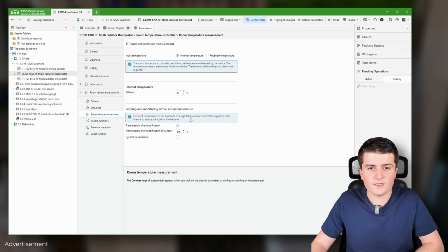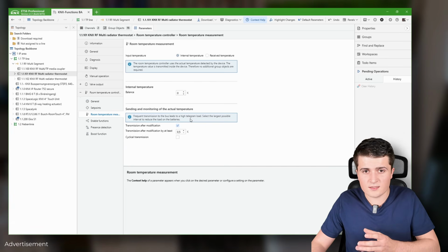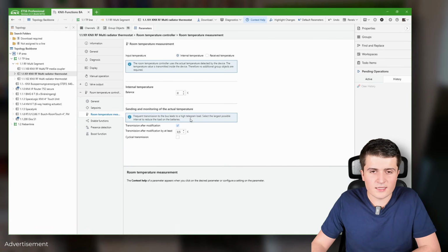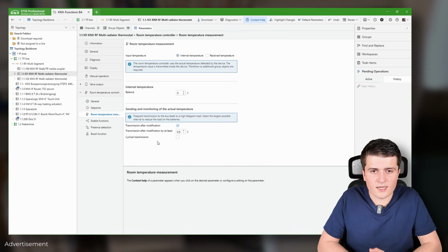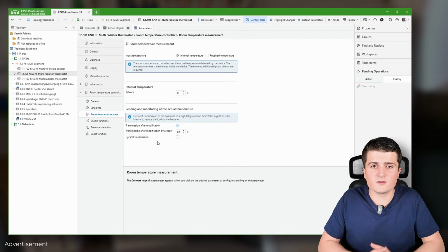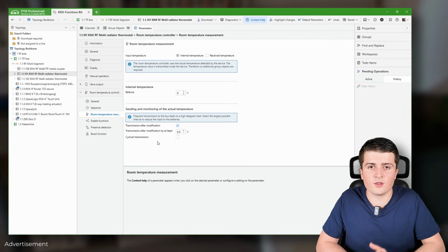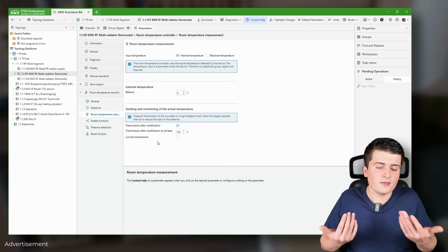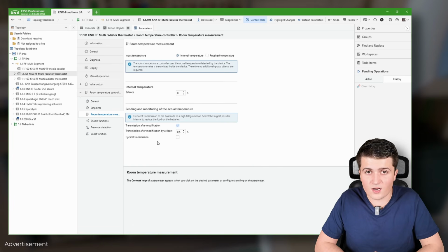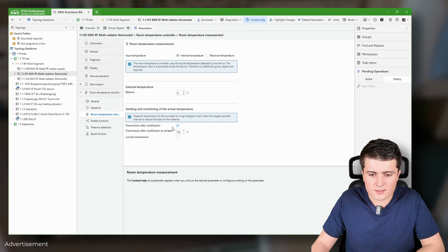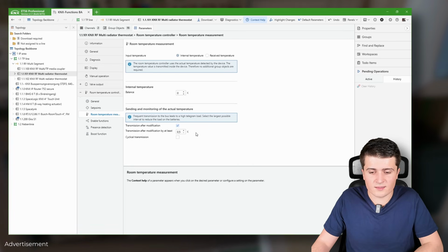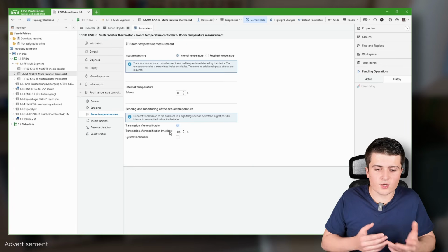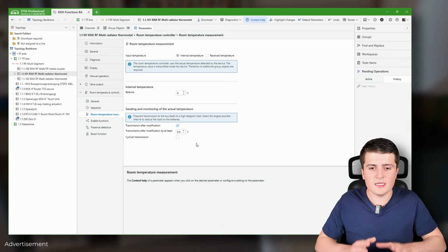Here we can also specify when the device should send the current temperature onto the bus, and here it should be considered that you don't use a cyclical transmission, because then obviously the load on the device and therefore also on the battery is higher, and the battery definitely won't last longer. So therefore I will stick here to transmission after modification and after at least a difference of 0.5 Kelvin, maybe also consider 1 Kelvin. So those are the basic settings.